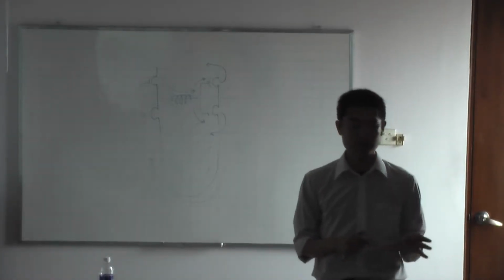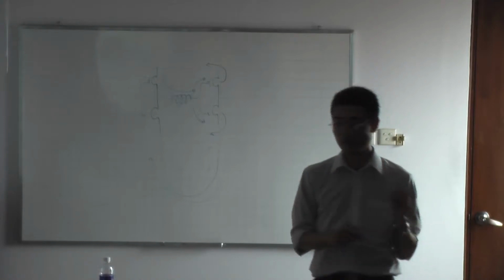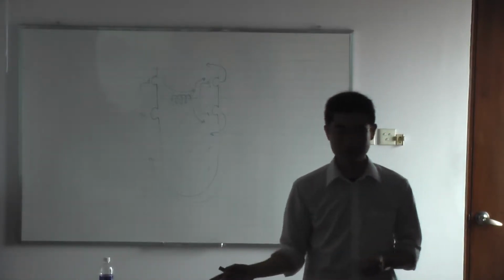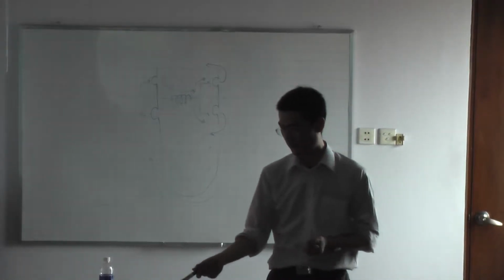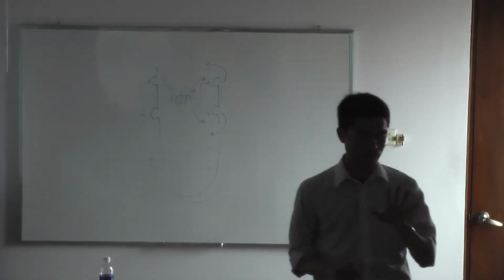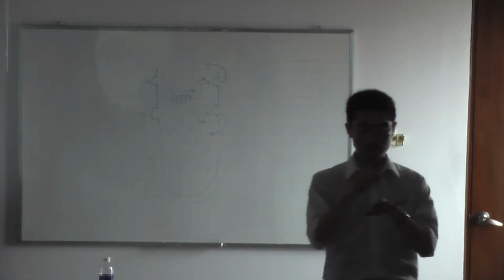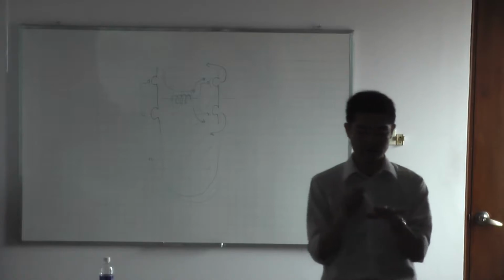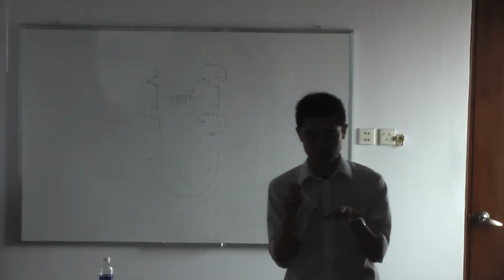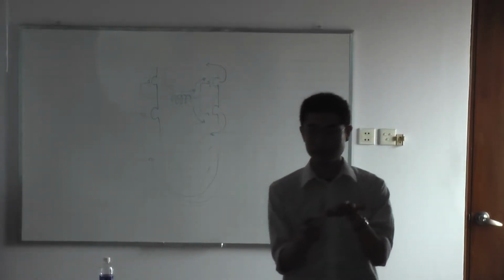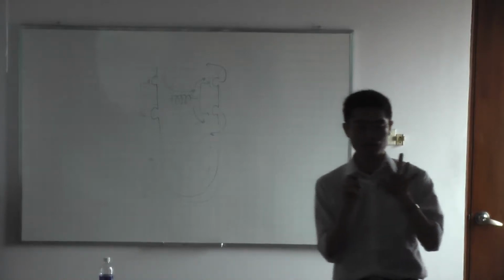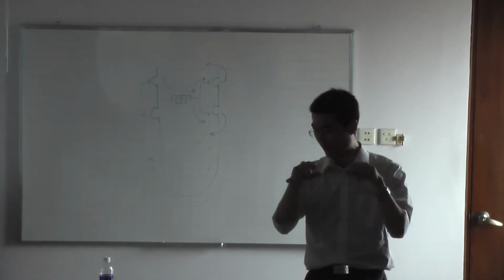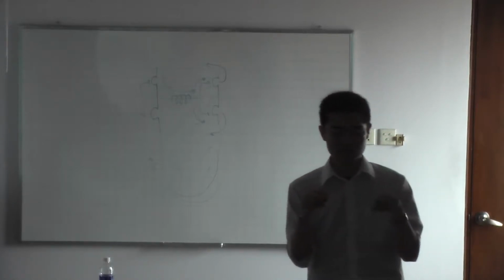So for very high-speed signals or RF signals, we have to use the prober, not on-board. And this prober is also expensive. This blue prober means we have 5 needles, and we have 2 signals surrounded by 3 grounds. So we call it GSGSG, meaning ground, signal, ground, signal, ground. So that we will have a return path from the signal to the ground. And the SMA terminals, we have 2 terminals, each with 1 signal surrounded by ground.